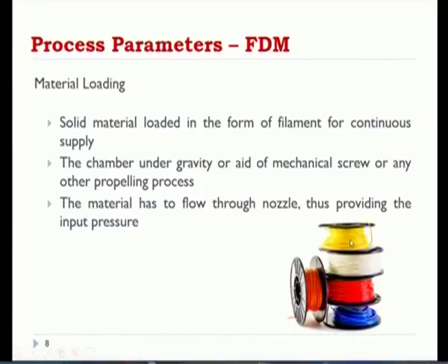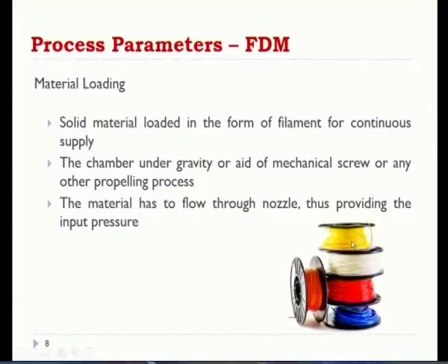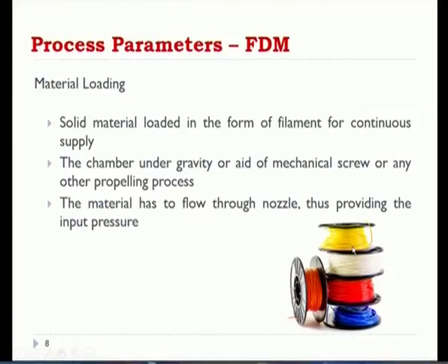They will measure the input at the moment. Say for example I need a product of 100 centimeter size, but for the initial 5 or 10 centimeter I need some color, say blue. They will measure according to that input filament itself. They will connect the different colors together and the input can be modified. You can have multiple color inputs, as well as different varieties of inputs, say pellets or granules, which we can also change.